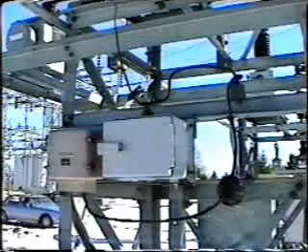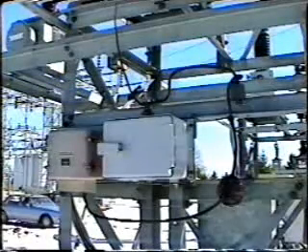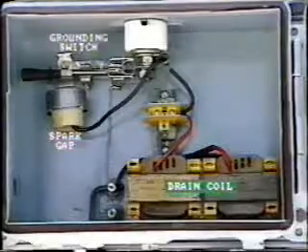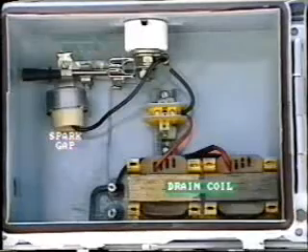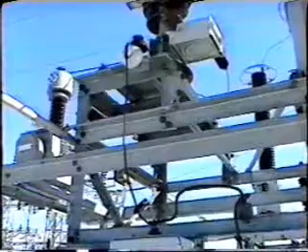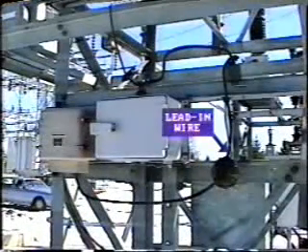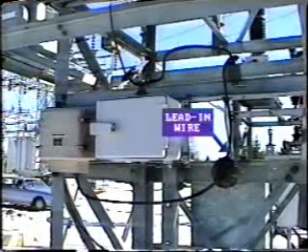If the VSWR test indicates that there is difficulty in matching the impedances, then we must check out the LMU. First, close the grounding switch, then check the connections inside the unit. Coming down from the base of the coupling capacitor, you should see a single insulated conductor called the lead-in wire.